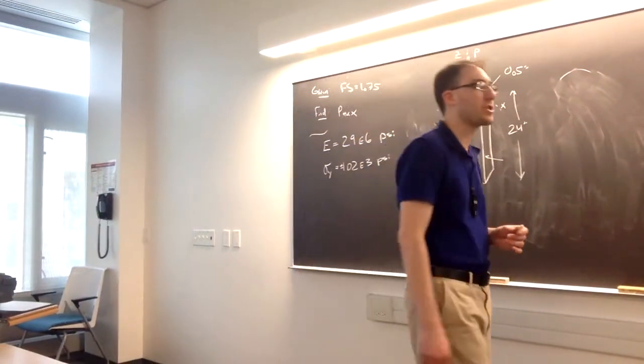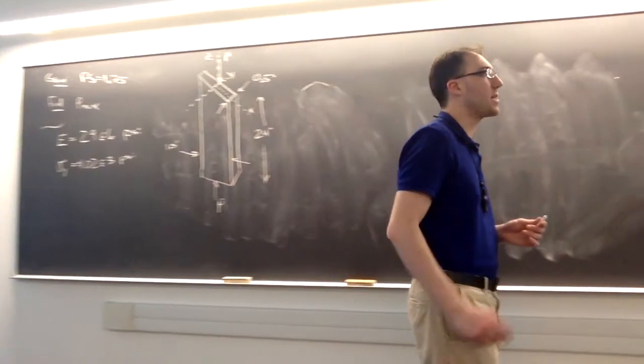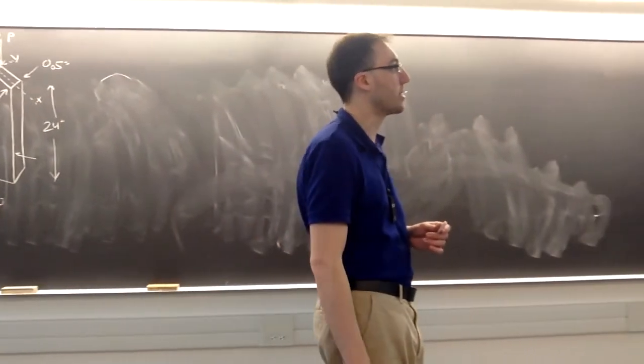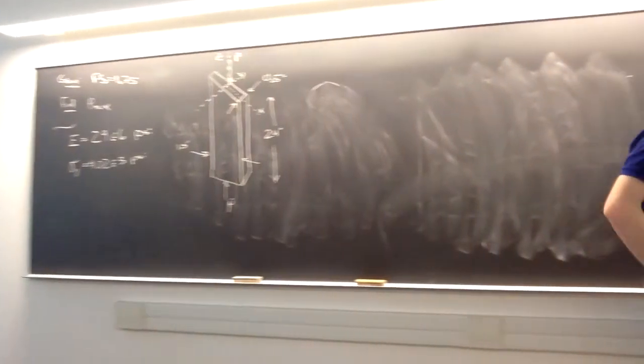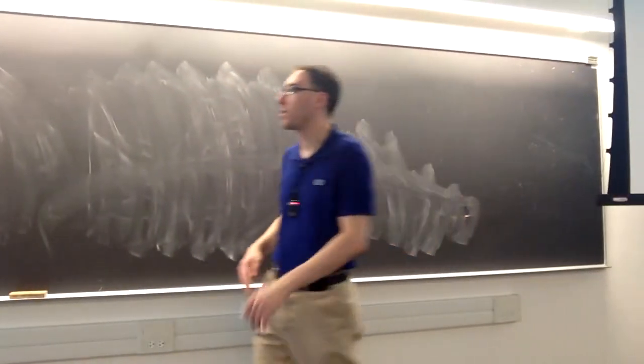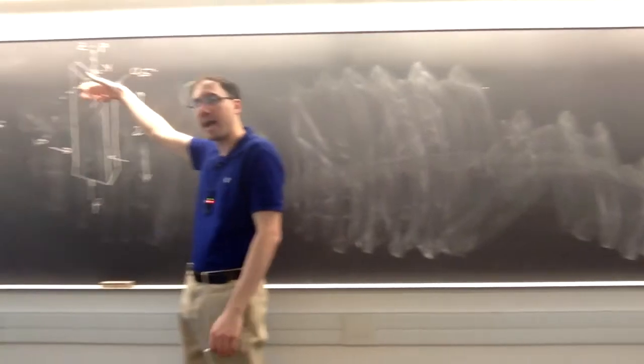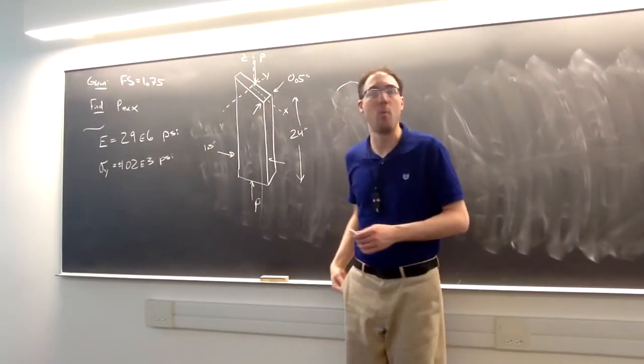So based on the picture, if we look at the left side, it's pinned along that direction. But if we look at the other side, it's fixed. And this is going to affect the effective length depending on if we're looking at buckling around the x-axis or buckling around the y-axis here.